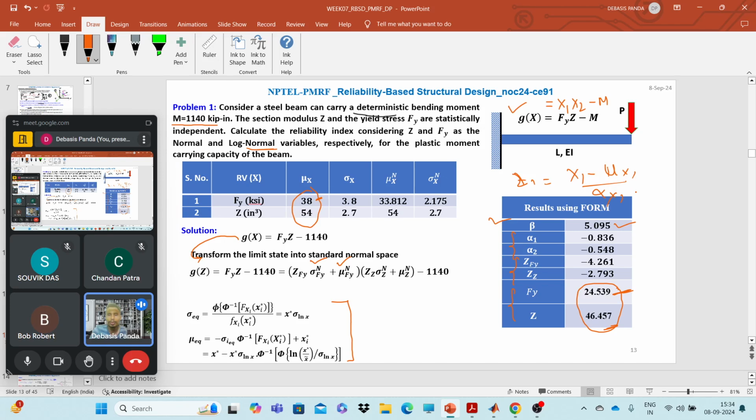So first we need to do the first order reliability analysis using Rackwitz's algorithm. We did it and we get these values. These are the prerequisites for the SORM problem or the Breitung model. Now, once we have these values, we need to first form the R matrix. Recall how we can formulate the R matrix. First we need to calculate the R naught matrix. The R naught matrix will contain the last row as the design point direction cosines.